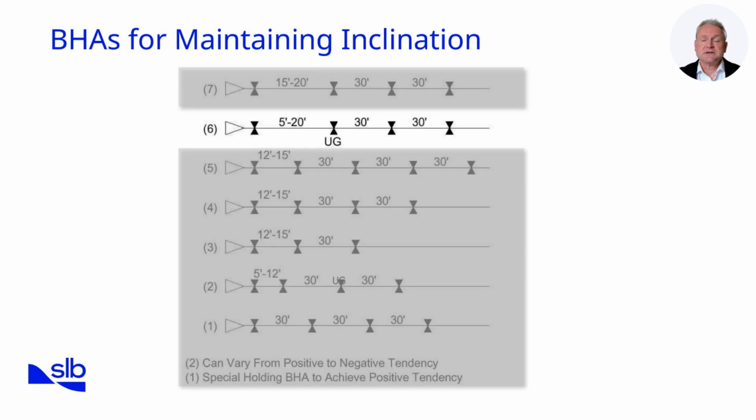In practice, slight changes in hole inclination often occur, even with a good choice of locked BHA. However, the objective is to get a complete bit run without needing to pull out of hole for a BHA change. Experience in a location should give the DD the data for fine-tuning the BHA. Reducing the gauge of the second stabilizer gives the same result as leaving the stabilizer alone, but increasing the distance between it and the near bit by a certain amount. However, for directional control purposes, the former approach is better.